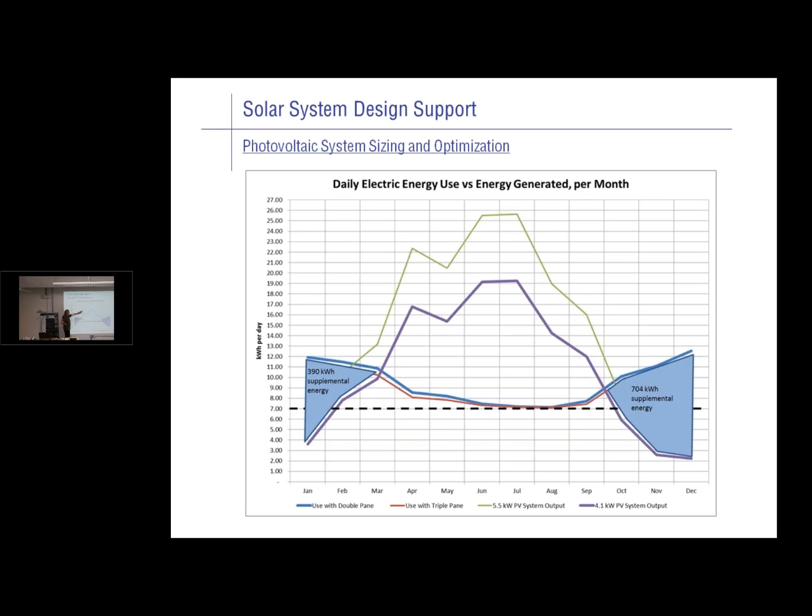And then layered on top of these load curves are PV output curves. And this is something that actually eQuest can do. I don't know if any of you have dived into that PV input aspect of eQuest. It's simplified, and there are many other tools out there as well. PVWatts Online will do it. If you use Solar Pathfinder software, that actually does a little bit better job because you can handle shading. eQuest does not simulate shaded PV surfaces. PVWatts does not simulate shaded PV surfaces, so they're idealized curves.